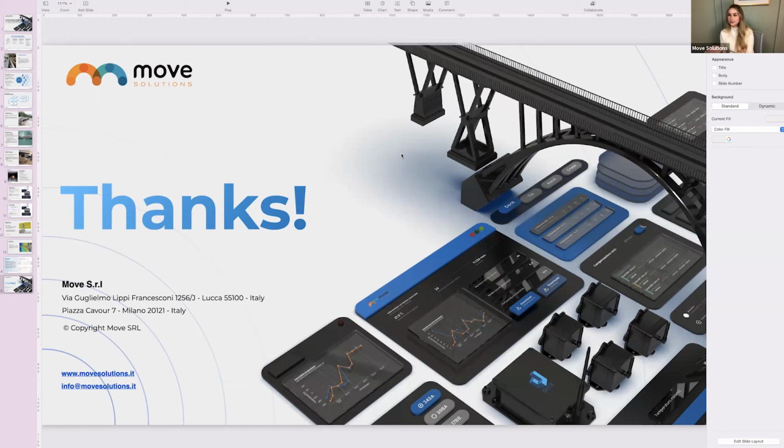Yes, in an ideal situation, of course. This is more of a solution when you have scour critical bridges. I know that, for example, the Pennsylvania DOT has a number of scour critical bridges that every time it floods, they have to physically go out and inspect the bridges. So it's a good way to monitor when you know that there is a scour problem. Understanding it before would definitely be the ideal situation.